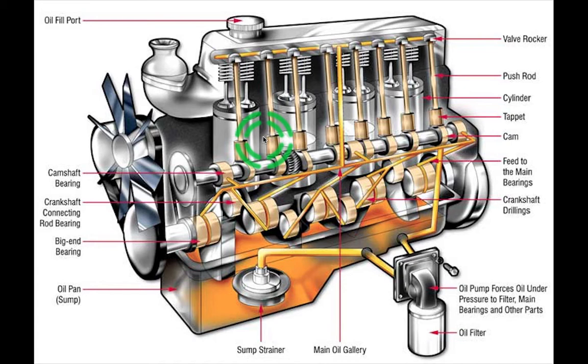So you have to have a general basic idea of how the lubrication works, because first thing, you can't run an engine without oil. Not for 1 second, not for 2 seconds, not for whatever it is. You can't run it without oil, period. Without water, yes, you can run it till it reaches a certain temperature, to test it out. Although it's not really recommended, you can do that. There's no harm. Don't listen to people who say you can't do it. If you are in need and you have to do it, just do it. Don't worry about it. But don't let it go beyond, let's say, 70 degrees and stuff like that.